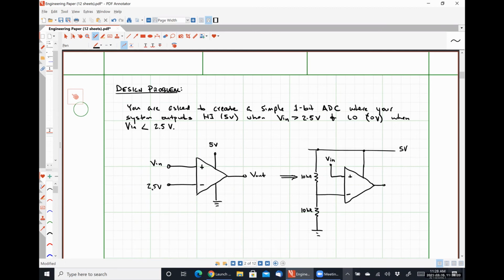I don't know how many of you took me for Circuits 1 way back in the fall and are just now taking Circuits 2. I'm not sure what Davis and Lewis did last quarter, but typically speaking, most of the op amp circuits that you've seen to this point should have had all of the resistors having a value in the kilo ohm range. Even though everything we're dealing with usually involves resistor ratios, we always wind up putting things in the kilo ohm range because that means that the resistor values are significantly smaller than the input resistance so that we don't see current branching off and flowing into the input terminals.